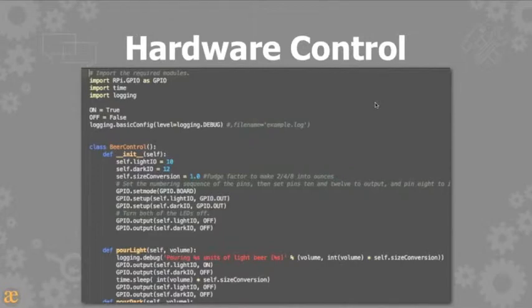It turned out that if we opened both of those relays at the same time, that causes big power fluctuation, which caused the Raspberry Pi to reset. So rather than actually fix it in the hardware, I just made the decision that we'll only pour 1 beer at one time. So it's kind of a slow process anyway, though it should be fine.